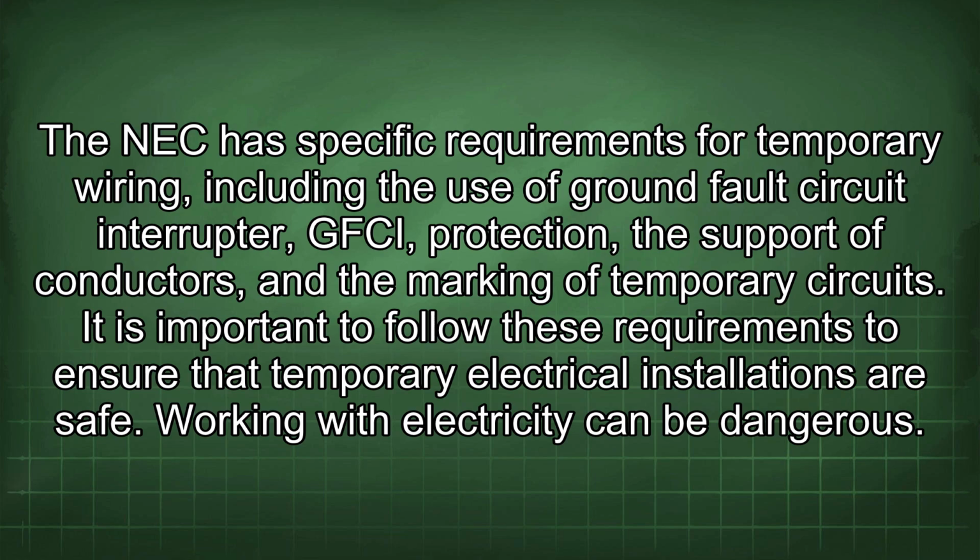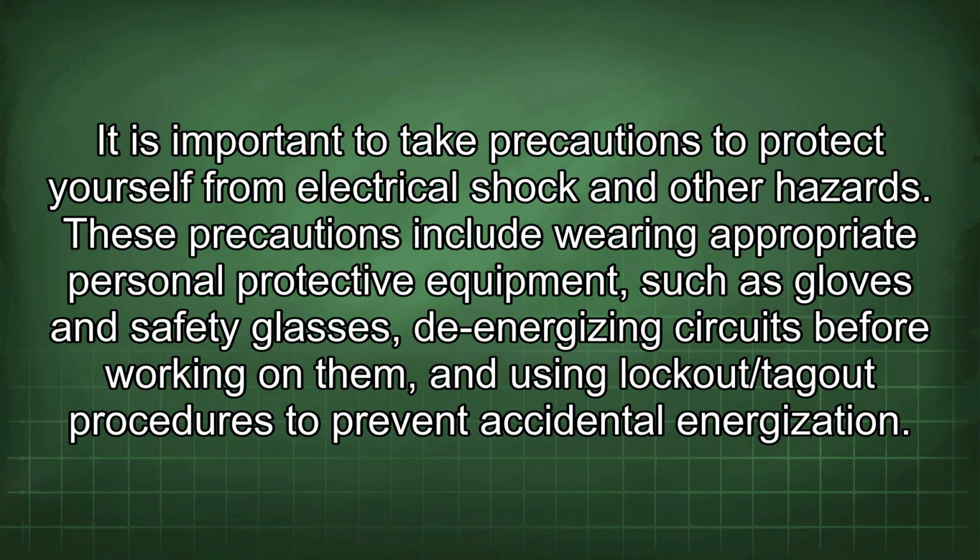Working with electricity can be dangerous. It is important to take precautions to protect yourself from electrical shock and other hazards. These precautions include wearing appropriate personal protective equipment, such as gloves and safety glasses, de-energizing circuits before working on them, and using lockout/tagout procedures to prevent accidental energization.